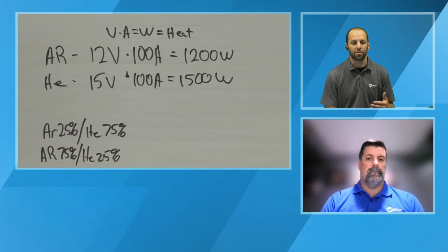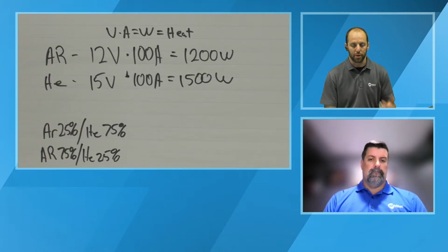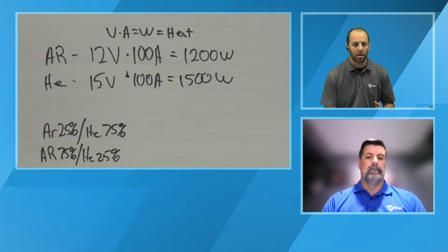So if you're looking for these functions and understand how to utilize them appropriately, that's where it's probably time to look at stepping up into the Dynasty platform, where you can get more of the functionality: the frequency control, extended balance ranges, the different waveforms. Then, taking it a step further, if you have a Dynasty 210 or 280, you can get the expansion card, or on the 400 and 800, that's built in, and you just go into the menu and activate that functionality.